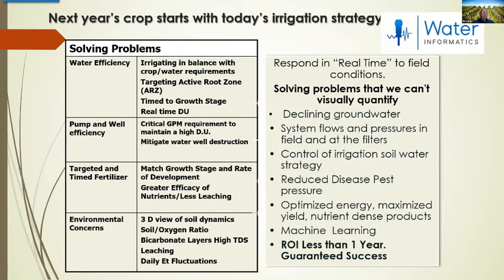We've seen carbonate layers in wells that can be up to a half to a full inch thick, and it's really difficult to open those up. The other thing is that these wells will biofoul. If you're pulling too hard on them, they'll break, because of the differential in pressure between standing and pumping water level. The top part of the well, where the well seal was, will actually cause that well to snap, and then you have to go in and fix that.